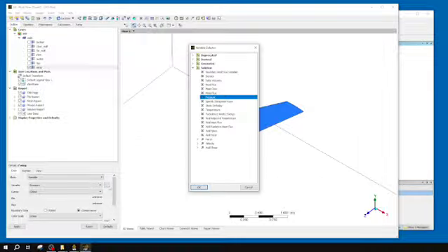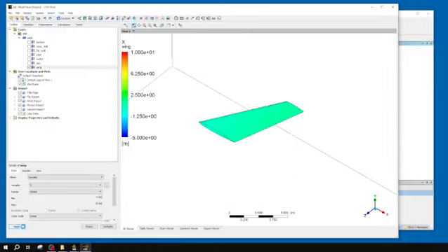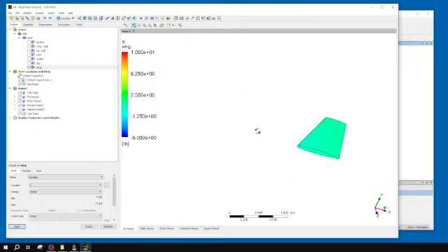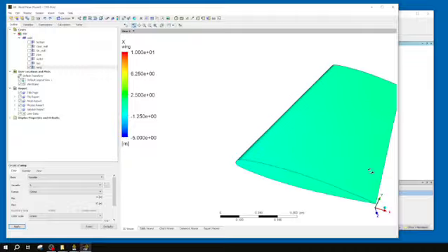Right, so I can have wall shear or a specific direction of wall shear, same with velocity or forces. These are all considered solution variables. I can have geometric variables. So if I didn't know how far I put something, I could display x's, and I'm just going to display that real quick. Right, so I have different x values, which is downstream. So you can see everything's pretty close to 0. It might be more valuable if I actually go y, because that has less of a range.